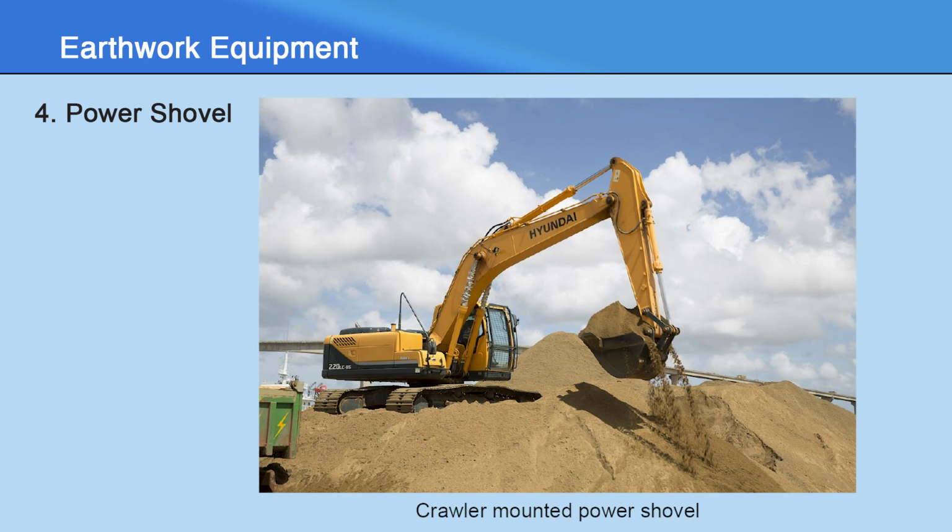The size of a power shovel is determined by the size of its bucket or dipper, which varies from 0.375 cubic meters to 5 cubic meters. The basic parts of a power shovel include the track system, cabin, cables, rack, stick, boom, footpin, saddle block, and bucket. So certain technical terms related to power shovels are the boom.